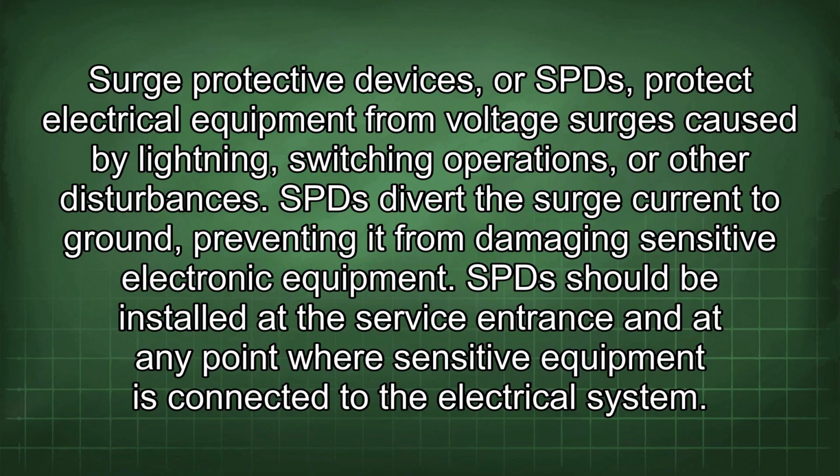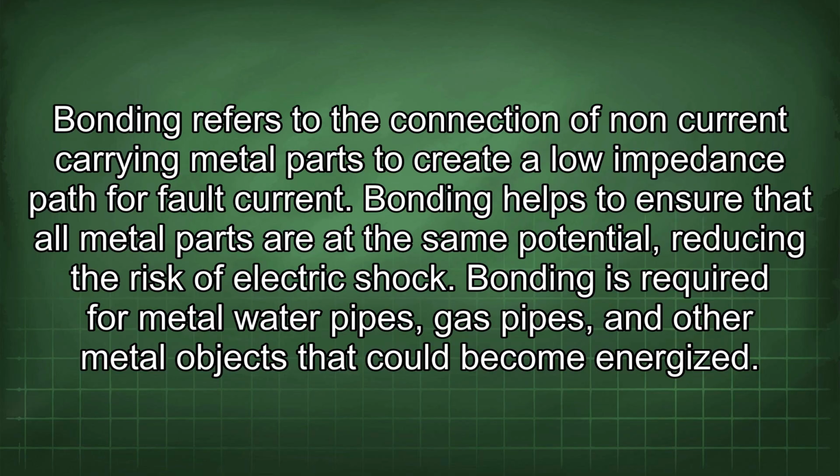Surge protective devices, or SPDs, protect electrical equipment from voltage surges caused by lightning, switching operations, or other disturbances. SPDs divert the surge current to ground, preventing it from damaging sensitive electronic equipment. SPDs should be installed at the service entrance and at any point where sensitive equipment is connected to the electrical system.